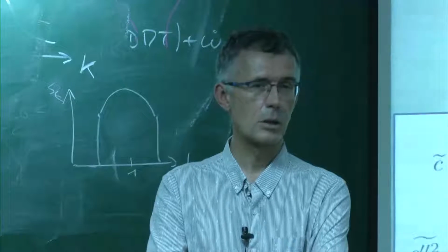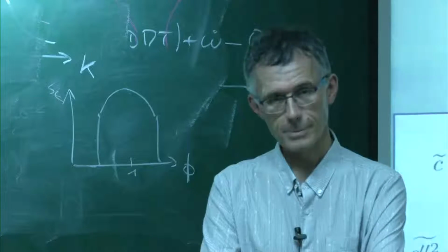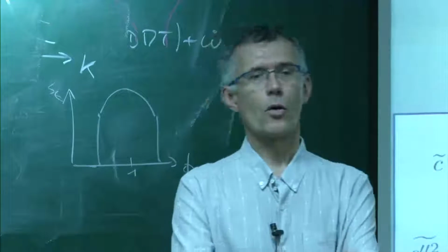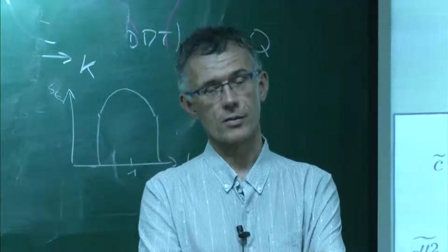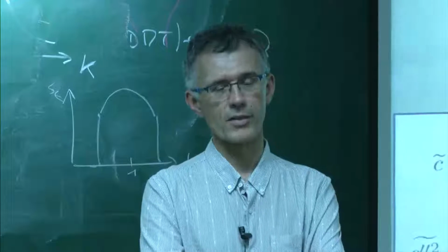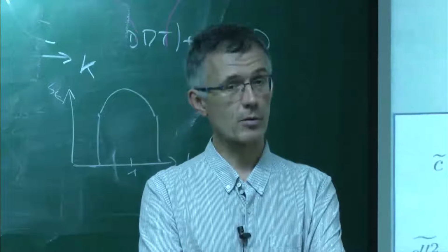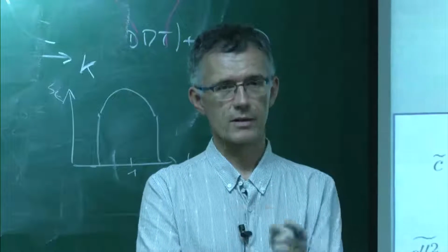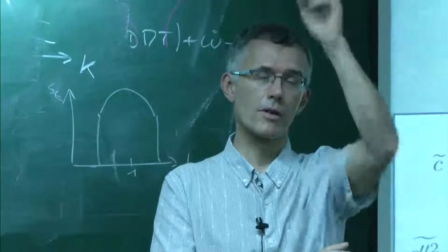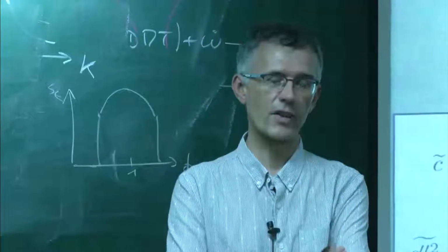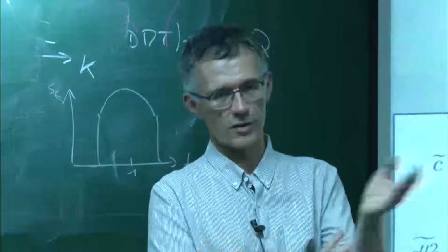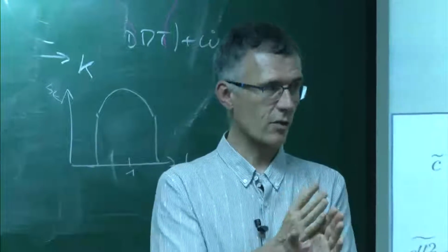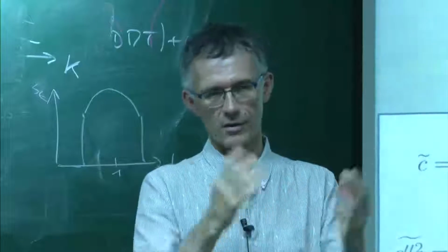In the EDC concept, I know the temperature shoots up beyond 5,000. Why is that? Oh, okay. The problem of the temperature going too high is not a physical problem. Usually it's a numerical problem: the reaction rate has become too large at one point, going to crazy values, and then the temperature overshoots 5,000. Normally it's a lack of resolution. We are exactly in what I was describing before. If the flame front gets too thin, then the code just explodes.